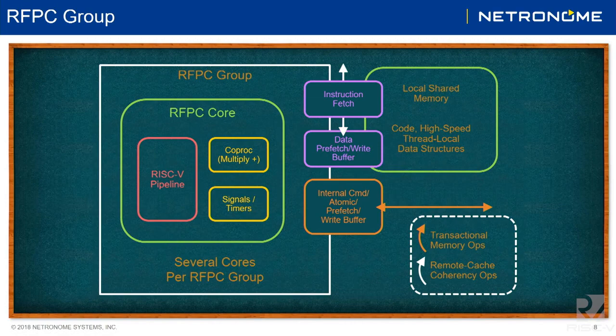We also use the custom instructions to support the transactional memory operations. That's the method we're using to set up the instructions and return the results of the instruction back, along with the signaling method. We also need some level of user mode and low-level machine mode operation, so we're supporting both of those.